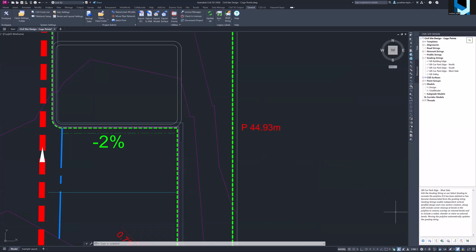We're going to head down to the bottom of tool space, and you'll see that there's this sort of Cogo point icon. You can click on that depending on which version you're running. If you're running V24, I think, you might find that the button is there, these options are there, but it doesn't look like a button. There's no black marker or black arrow. We're going to click on Create Cogo Point.